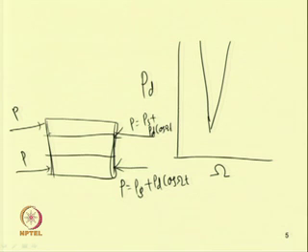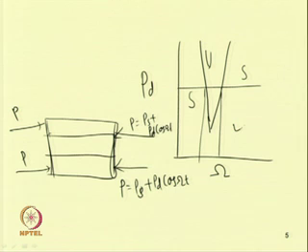We have seen that for certain values of P d and omega, for example, for this value of P d, the system becomes unstable at a frequency corresponding to this. Again the system becomes stable at a frequency greater than this. So, this region is stable, this region is stable, and inside this curve it is unstable. These are the parametric instability regions we studied in case of sandwich beams in the last class.